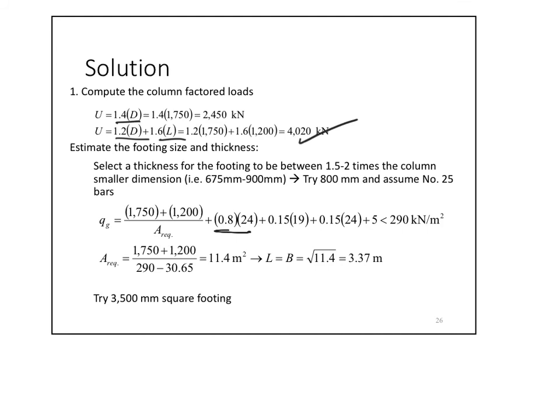of it. So I have, this is the footing itself. I assumed it to be 800, right? And the fill above it, and the slab above it, and the load above it. Now everything here is unfactored. To do this, I'm going unfactored. Okay? And then what is not known is the area.